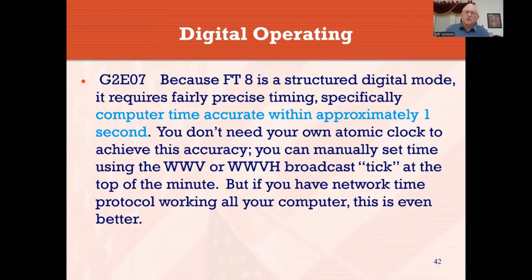FT8 is a structured digital mode. It requires very precise timing. Normally, you have to be within plus or minus 1 second of Coordinated Universal Time because it is timing sensitive. It knows that on the 1-second mark, certain things are supposed to happen. At the 2-second mark, some more things are supposed to happen. So it has timing in order to make it all work together. You don't have to have an atomic clock to do that.